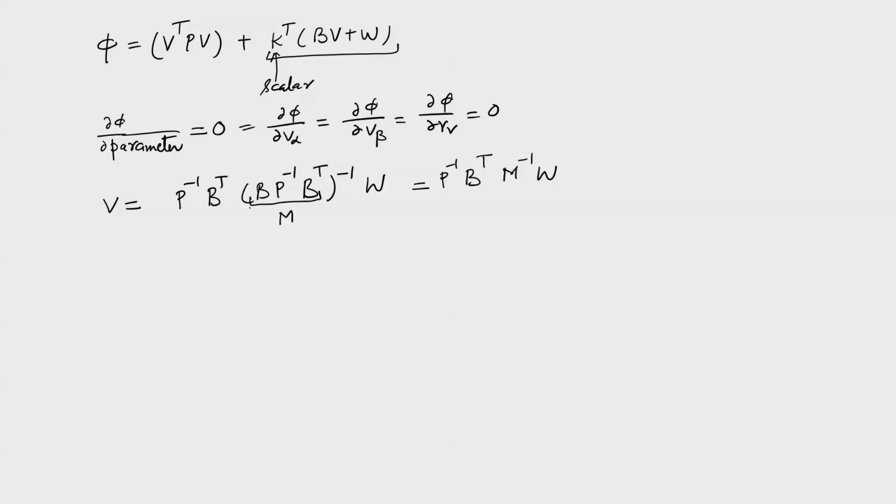Let us take the same example of the three angles of a triangle. There, can you use this formula to find the solution? Try yourself and find out that V alpha, V beta, V gamma will each be equal to E by 3. What is E? E is nothing but alpha bar plus beta bar plus gamma bar minus 180 degrees, or you can write it the other way around also. Why? Because the error could be positive, it could be negative also, no problem. So, you should get this answer.